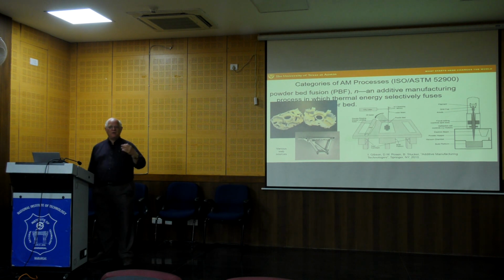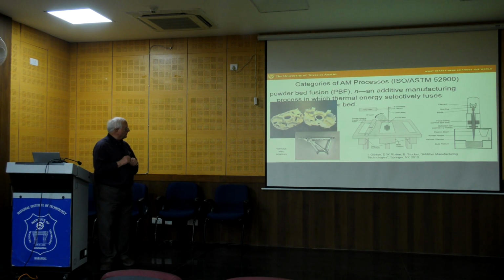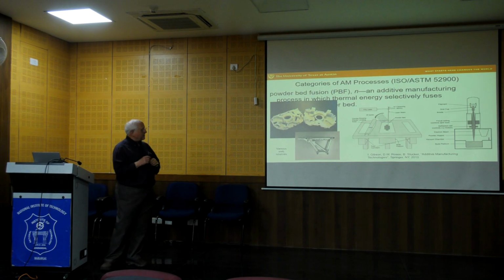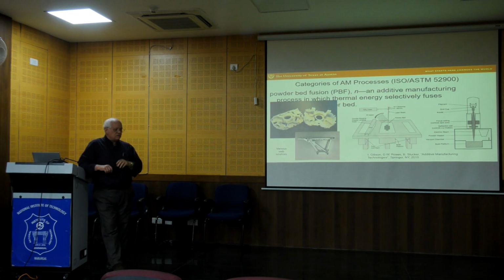And also, this has a beneficial effect on the surface finish as well, because the support structures leave behind surface artifacts, which do not appear with these parts. And then lastly, of course, nylon is a classic material, a feedstock for powder bed fusion in polymers. And nylon has actually reasonably good service properties in terms of the mechanicals. And so it's a very good part for service objects as well.